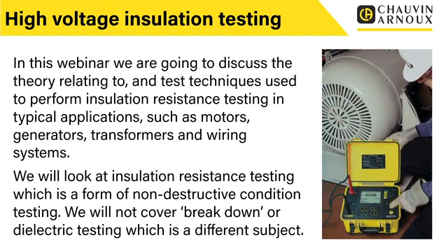We're not trying to prove what voltage we can use to break this equipment, or what voltage we can use to get the insulation to flash over under surge conditions and things like this. What we're doing is using these high test voltages, this insulation resistance test, to non-destructively test and monitor the condition of insulation. So that's where this differs from something like flash testing or dielectric strength testing. We're not looking to break it down. We're not looking to put this insulation under so much stress that it may get damaged. We're looking to do non-destructive testing so that it's repetitive and we can continually monitor and compare the conditions over time.